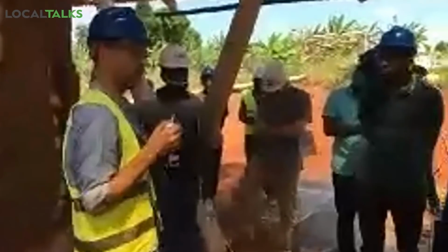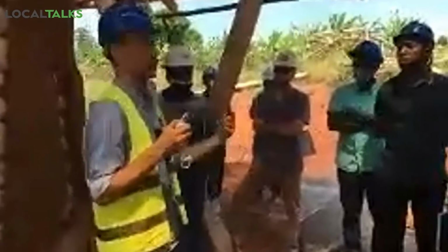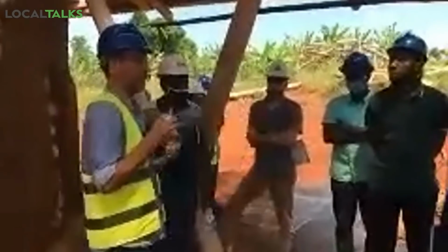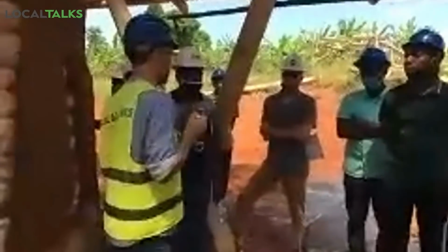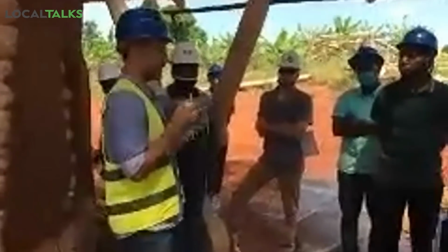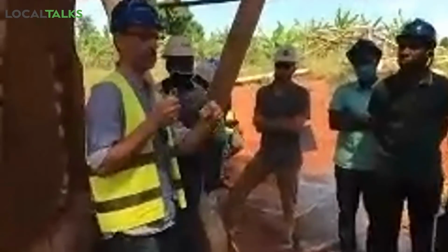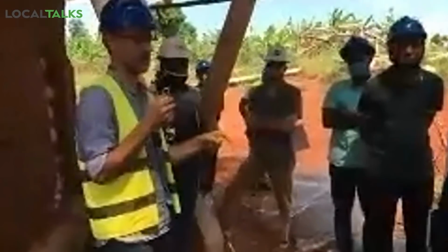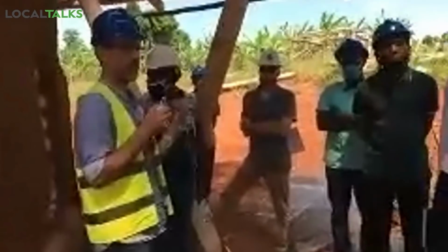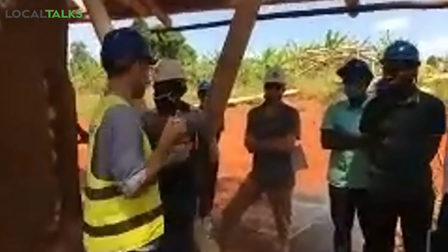And number two, and that is really an important aspect, we always need to think about what is the process of repairing damages and of improving, of maintaining a building. There is nothing easier to maintain than earth plaster. What is very complicated is to fix cement plaster that has broken out and that then needs to be painted over, and by the time you paint it over, you actually need to paint the whole wall and you need to go and buy 20 liters of Plascon paint. We don't need all of that. We can actually repair locally in certain areas with material from the site. That is one of the big strengths that I see in earth plaster.